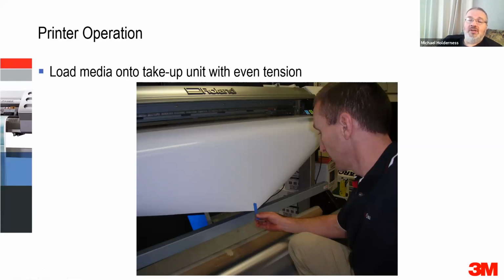The trouble with 2 is that you can end up with it skewed. So even if you're a millimeter or 2 out when you put those 2 pieces of tape on, you'll find that the roll winds itself sideways and will telescope as it winds up. To avoid that, just use 1 and it will tend to self-center it. So all you've got to do is, as the printer starts to print, make sure that the roll, as it winds around the mandrel at the bottom, has its edges coming around cleanly and it will wind up beautifully. You can do it with 1 piece of tape. I tend to use 1 piece of tape purely because I know that I'm going to get a nice tight roll.